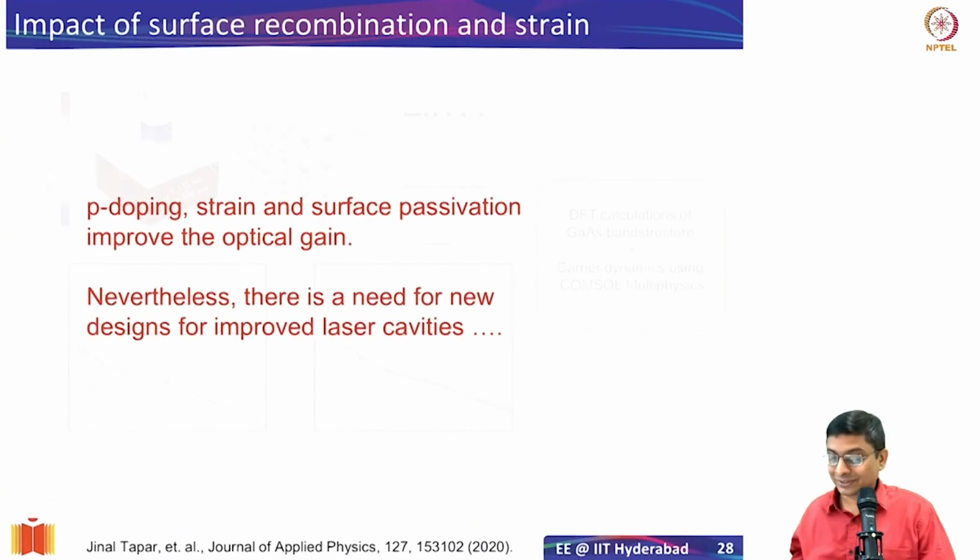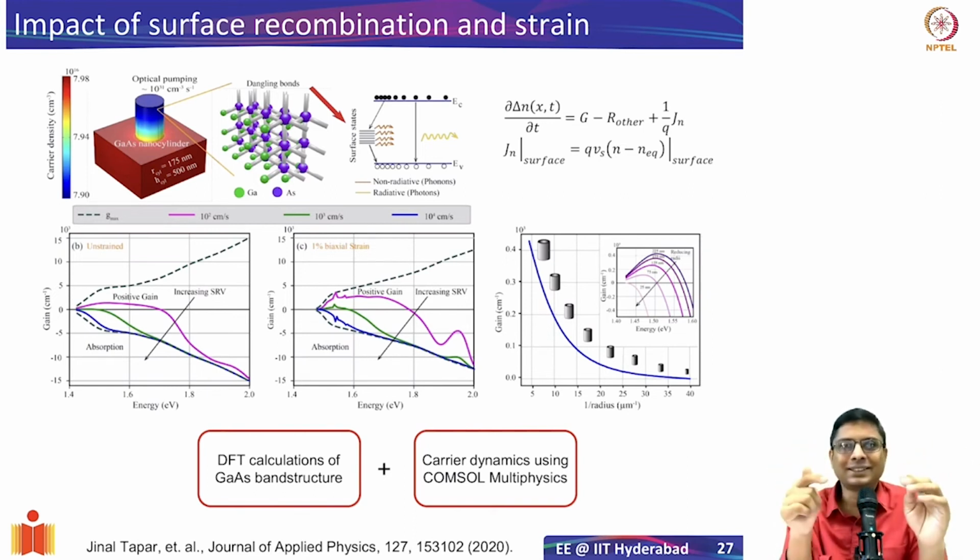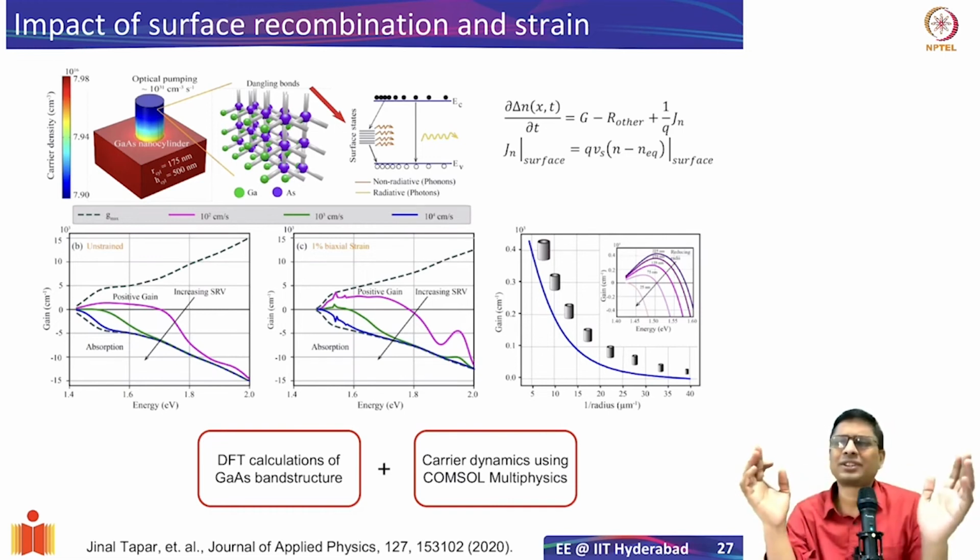The question was, why is the surface recombination given in terms of velocity? Generally, recombination is described by recombination lifetimes. Well, the idea here is that if you make a nanostructure, there are these surface states. I didn't really talk about the details, but essentially the number of surface states is going to depend on the surface to volume ratio. So if you have a big structure, the surface is not really that significant. You don't have to worry.